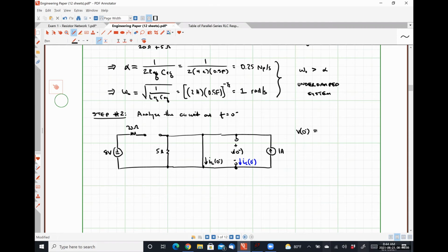So another way of stating that would be the capacitor is in parallel with the inductor, which looks like a short circuit. So the voltage drop over the short circuit is 0. Therefore, the voltage drop over the capacitor has to be 0. But your way of looking at it from no current flowing through the resistor, meaning no voltage drop across the resistor, is perfectly correct as well.